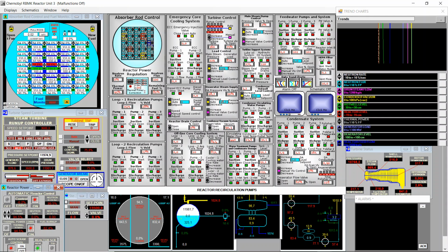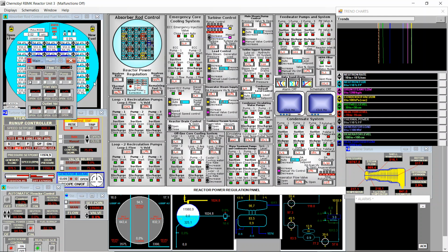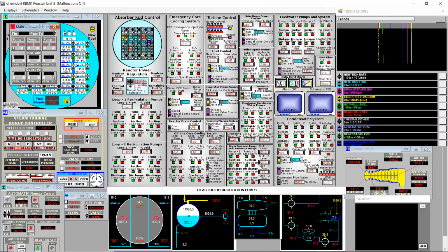And this is the correct setting. Loop 1 and loop 2 need to have 2 pumps each, not 3. We see the void almost equal. Maybe we'll trim a bit the void of loop 1. Just decrease... Oh, okay, it's the contrary. I should decrease flow in loop number 2 to increase a bit the void.